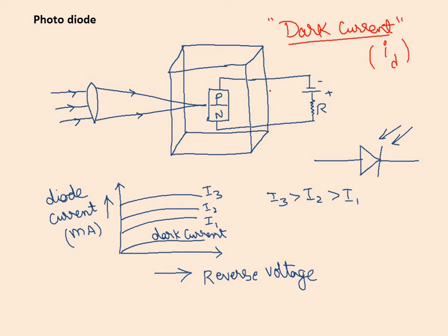When light is incident on the diode surface, additional electron hole pairs are formed. But since the concentration of majority carriers is much greater than that of minority carriers, the percentage increase of majority carriers is much smaller than the percentage increase of minority carriers. Hence, we can neglect the increase in majority density and consider the radiation entirely as a minority carrier injector.